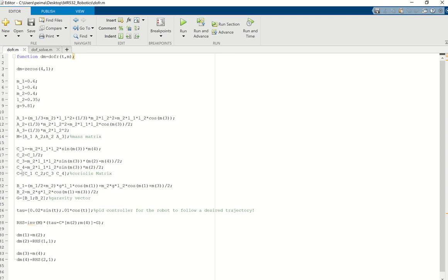I'm just going to show you the properties because it's too much at this undergraduate level. This is the Coriolis matrix, C and Q dot, and B is the gravity matrix, B1 and B2, a vector, I'm sorry. I said this is the control input, just some simple things to make a simulation, if you remember from the previous class. But now in this class, I'm going to fix this and design the PID controller to push the robot to the set point that we want to go to, okay?